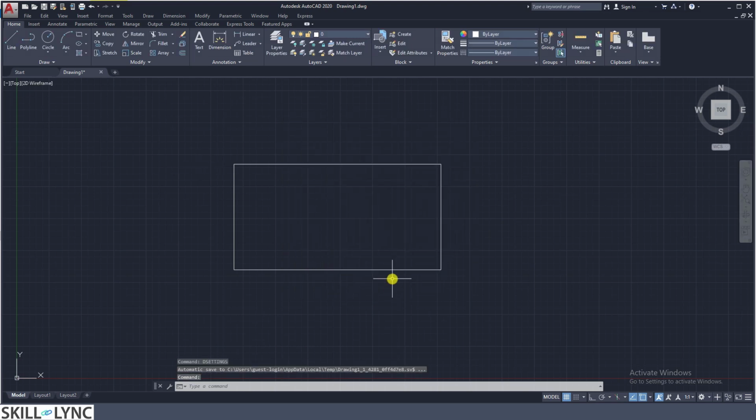So now we have enabled all the options. Now let us look into the circle again. As you can see, here you have multiple commands. You have the different nodes, and then you have the midpoint here, and then this command says it's perpendicular to this line, and here you have the end point, and it also shows the distance from the midpoint, and then again snapping to here, and then it also shows the center point here.